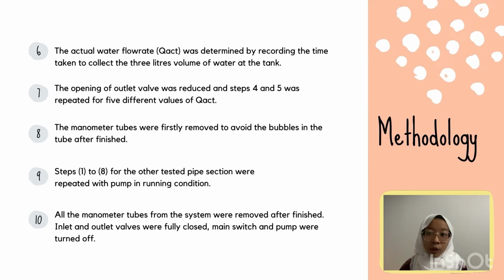All the manometer tubes from the system were removed after finishing. Inlet and outlet valves were fully closed. Main switch and pump were turned off.